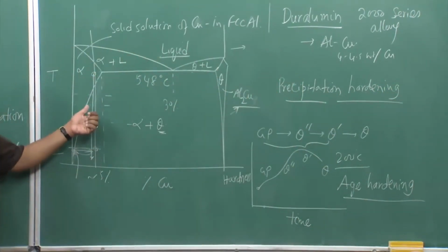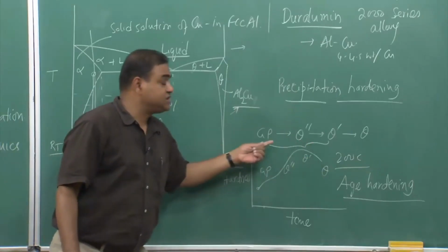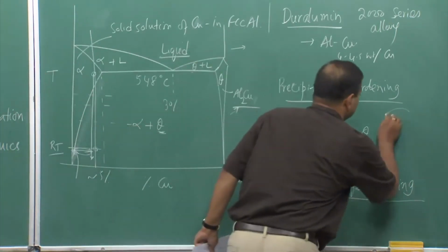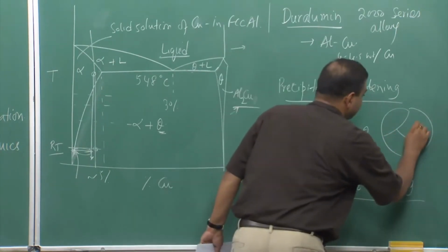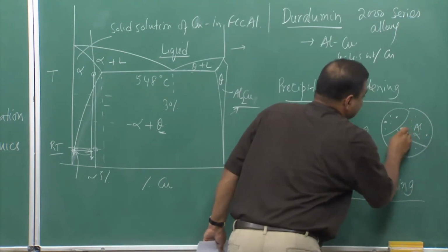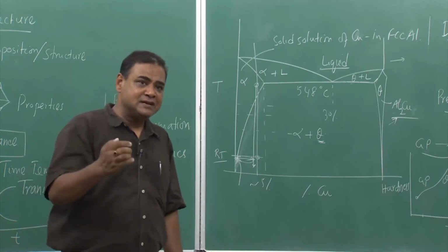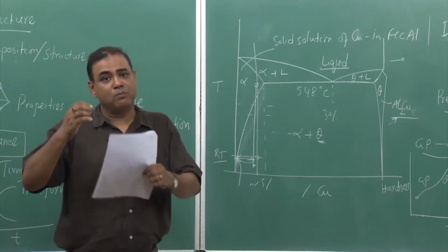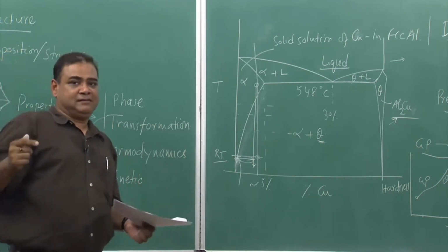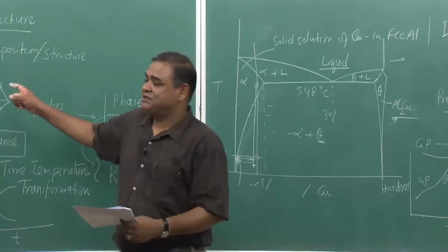Precipitation hardening. So, that means here we are fixing the composition, but we are changing the structure, because whenever we have these changes, we are changing the crystal structure, okay? And finally we are also changing the microstructure, because if those are the grains of FCC aluminum, which is the alpha phase, those precipitates would appear as small precipitates, and they would not allow the dislocations to move freely, because they hinder the dislocation movement, and whenever dislocation movement is hindered, we have an increase in hardness. That means more strength is required to cross that barrier, and that is what we get, an increase in hardness. So, this is a typical age hardening, which comes due to heat treatment, due to processing.